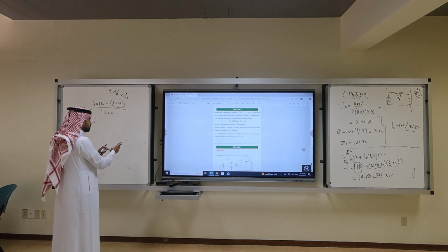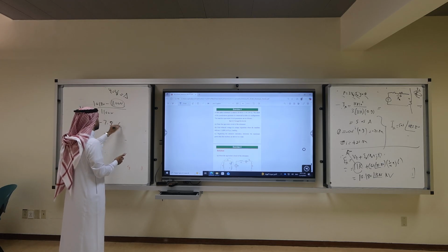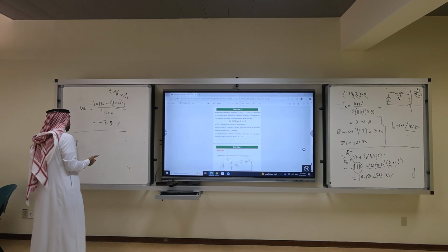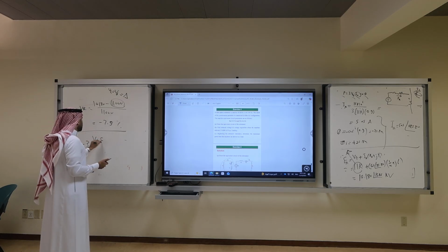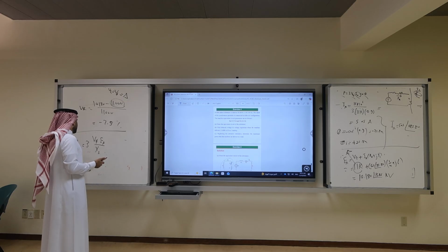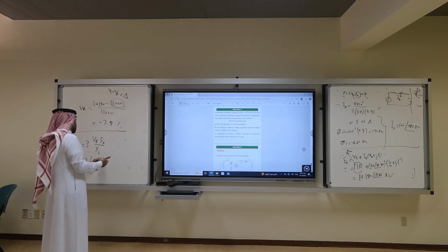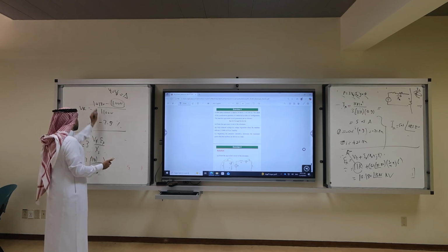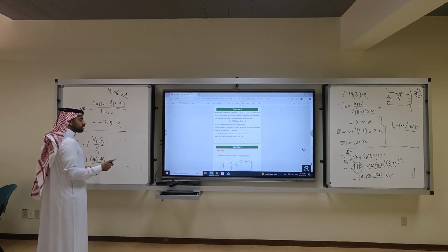Please watch the YouTube. 7.45, minus 7.5%. But that's the question. What is the maximum power? 3 V phase EA over XS, right? 3 times. What is the V phase? 11,000. What is the E phase? 10.18 divided by XS. Only XS, without the J.